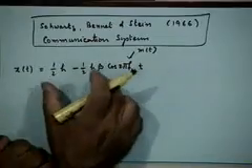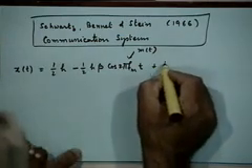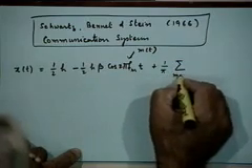It's not exactly a harmonic representation, as you will soon see, and which looks like this: half h minus half h, and there is a parameter beta which I will define shortly, cosine 2 pi fm t. Here I am assuming that your modulating signal m(t) is a pure tone signal. So m(t) is cosine 2 pi fm t. So that appears in this expansion, plus 1 by pi sigma m equal to 1 to infinity.